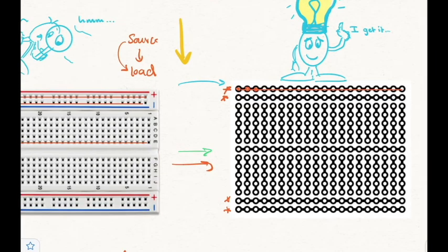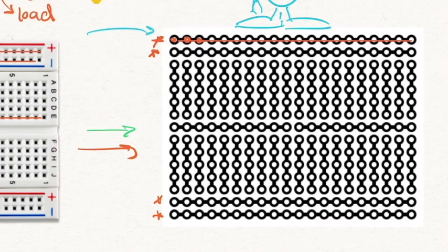So in reality, what a breadboard is, it's just metal strips going along inside of an enclosure. And now the enclosure has these holes that enable you to connect items like power sources there to actually operate your circuit. So what does this actually look like in circuits? Well, it enables you to connect a power source to the very end here and attach various wires, like say here, here, here, for example, that will bring to a load in a circuit. So let's imagine these are all going to separate loads in the circuit. It's all coming from the power here of a battery that, say, is attached.